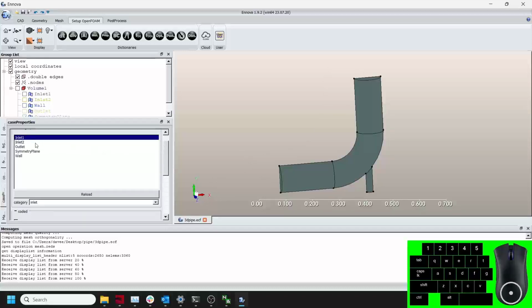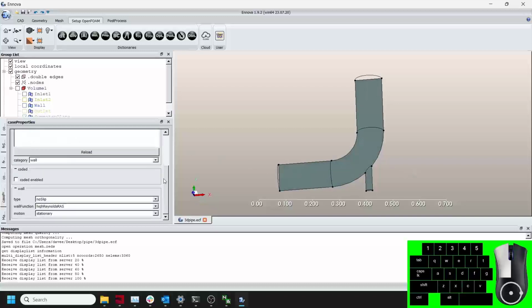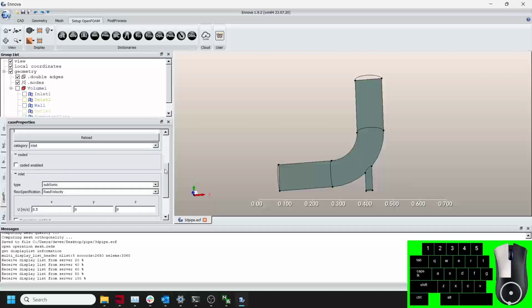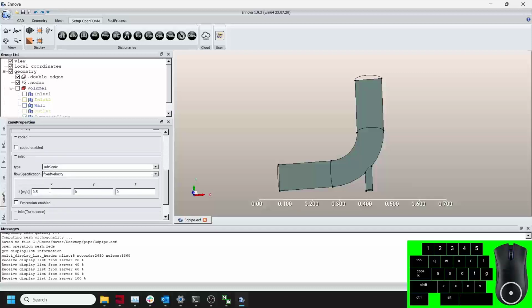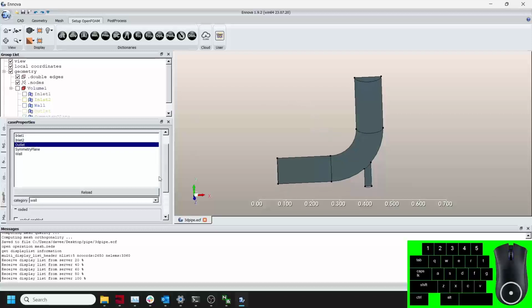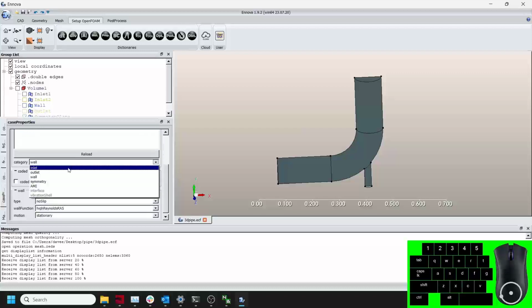Moving along to the second inlet, which is the smaller one, we have a velocity of plus 1.2 meters per second in y, as this inlet is normal to the y-axis. The inlets also prescribe the turbulence intensity of the inlet flow, which we are leaving to the default values of an intensity of 0.03 and an eddy length scale of 0.03. We then proceed to assign the outlet, symmetry boundary conditions, and lastly the non-slip walls. After this is completed, our model is ready to run.